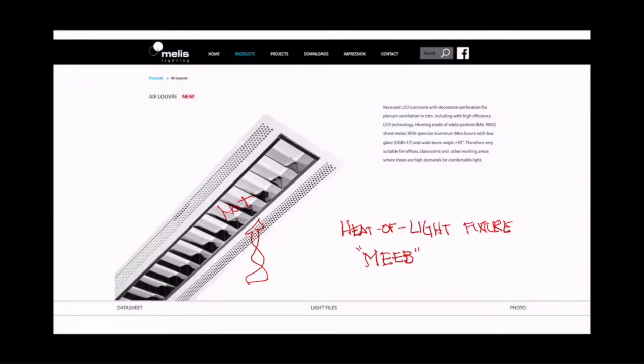But anyhow, the idea is that the light is hot anyway, the fixture is hot anyway. So if we're going to take air out of the building on a hot day, we may as well cool the light so that it doesn't add convective heat to the room by warming up the air around it. And if we have to exhaust the air anyway, we might as well exhaust the hot air that runs across the light. In reality, since Mead published this, lights have gotten much cooler and much more efficient. And this concept never really took off. So it's one of those things where it's only a Mead thing. I have no way of knowing if it's in the test or not, but if someone had asked about it, that's why we're talking about it.